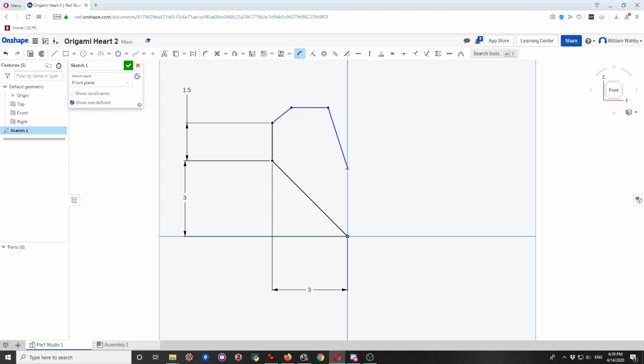So I still have a few things left to do. I'm going to want to choose the height of this. So let's go ahead and do that. I want, again, the vertical height there. So let's make that, I don't know, 1 centimeter for now. And I want this segment to end along the same line as this. So I'm going to constrain that total height here as well to be 1 centimeter as well. So now these guys are going to end in the same line.